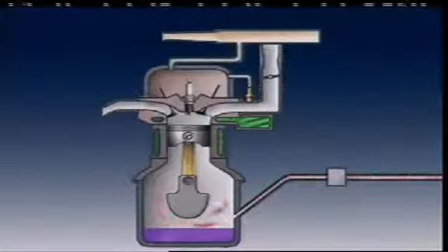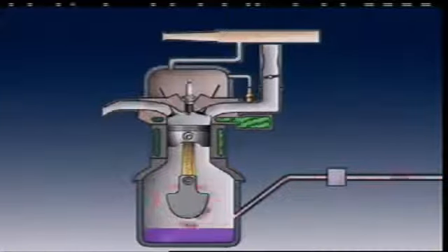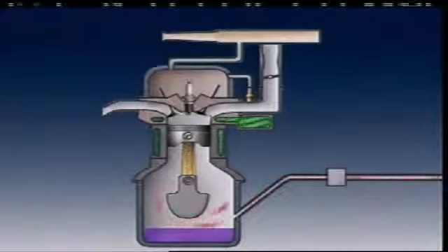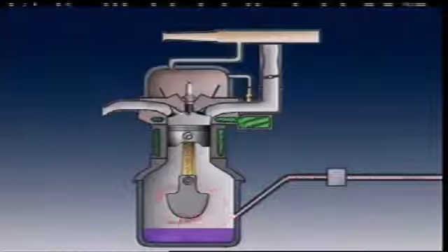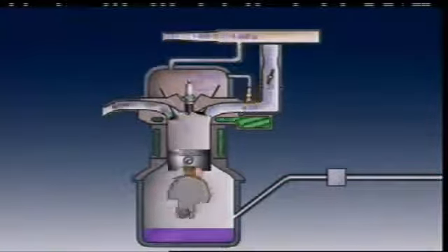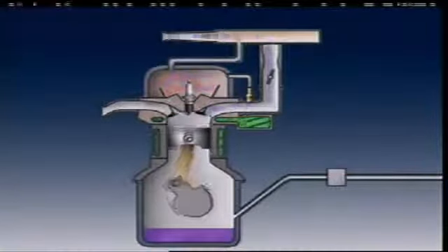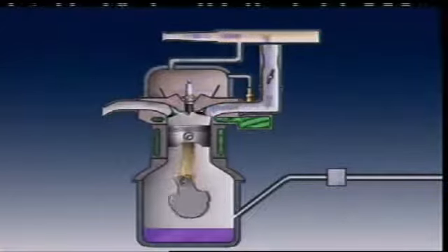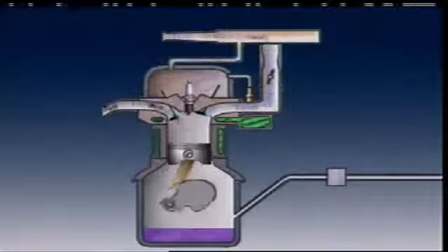Some vehicles use the engine crankcase. When the temperature of the fuel in the tank increases, fuel vapors are forced along the vent line past a liquid check valve and into the crankcase. When the engine starts, the positive crankcase ventilation system flushes vapors out of the crankcase and into the intake manifold, where it joins with the inlet air-fuel mixture. Once in the inlet manifold, the vapors are drawn into the engine, where combustion can convert them into carbon dioxide and water vapor.